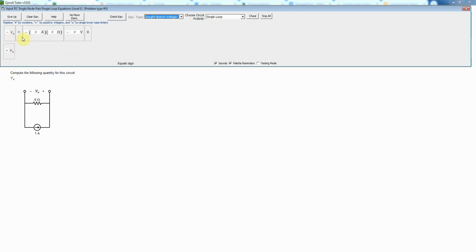So I'm going to need V naught equals, in this case, I'm just going to, actually let me just do this one in my head. So I'll put in the final number here. I can see 1 times 6 is just going to be 6 volts using Ohm's law. Okay, and again, I check that that should be a plus or minus sign in this case because the current's flowing into the plus sign. That's a passive sign convention. So I do need a plus sign here.